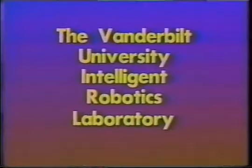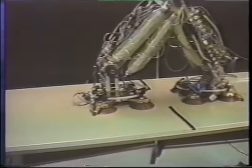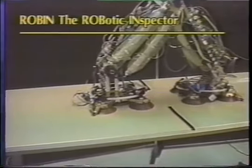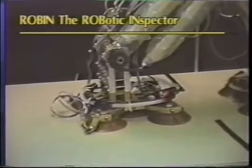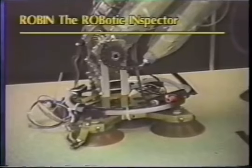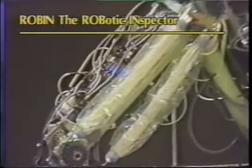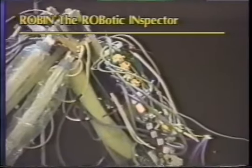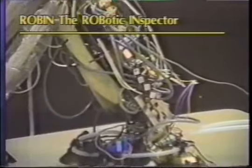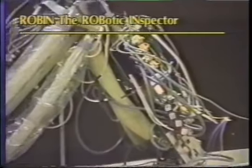Welcome to the Intelligent Robotics Laboratory at Vanderbilt University, where you will see our progress on the development of Robin. Robin is intended to be a vehicle for robotic inspection of man-made infrastructure, such as bridges, planes, buildings, and dams. Robin consists of two vacuum fixtures, or feet as we call them, connected by an articulated 4-degree of freedom mechanism. The motion of Robin comes from strong, lightweight pneumatic actuators called Robotuators.